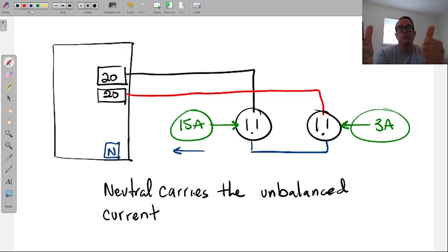The current goes into the loads. The current finds its way into that load and that load. And here's the other nightmare of this. They are now two different phases, A phase and B phase, which are not supposed to ever come into contact with each other. They are now part of returning, or backfeeding, into those loads. So we will destroy whatever is plugged into this outlet. That's one nightmare here.